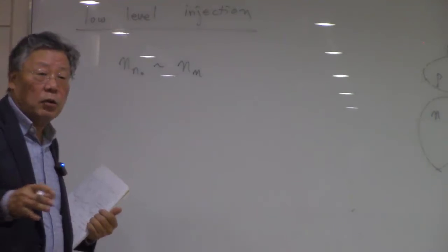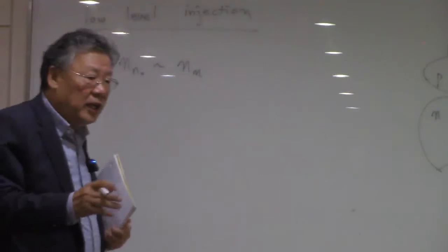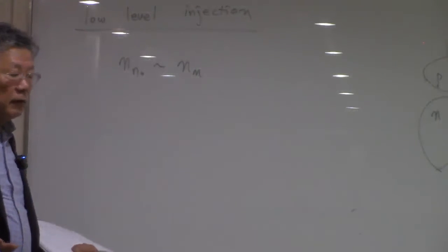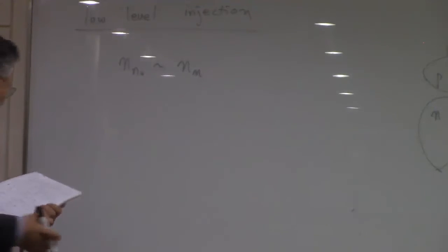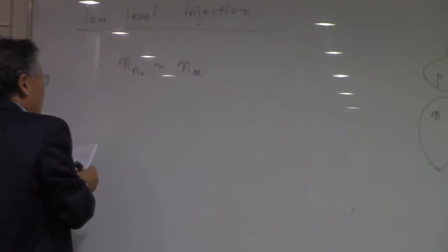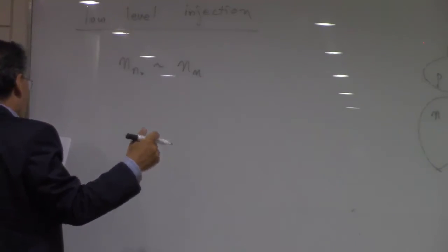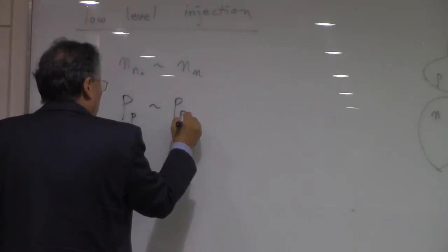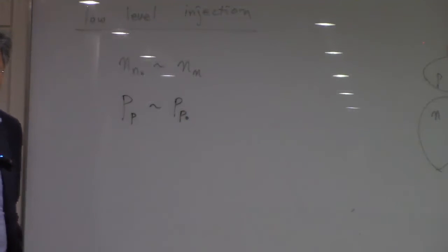And the Fermi energy is not going to be defined, because Fermi energy can only be defined in equilibrium. So if you suddenly apply the voltages to the junctions, then there is no Fermi energy anymore. We cannot define any Fermi energy. Anyhow, low-level injection means that with the application of the voltages to the junctions, the majority carriers are not going to change much from the equilibrium values. But we have a tremendous difference in the minority carriers.